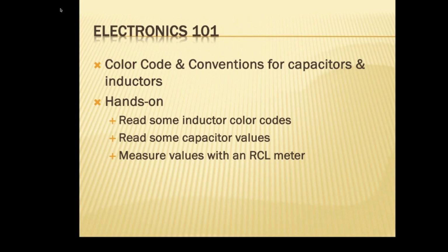Analyzing. Okay, it says very low resistance, which is okay. I'm gonna scroll. It's got 2/10 of an ohm resistance, very low resistance, that's fine. But it's 7.2 microhenries. Okay, so it's close. We thought it was maybe 6.8. Well, it could be 6.8 plus or minus 10%, so that would fall in there.